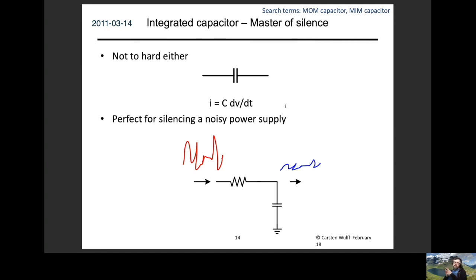They're pretty easy to generate, and you can get relatively accurate precision between them, on the order of maybe between 0.1 and 1% matching, depending on the size, because how well they match each other depends on the size.